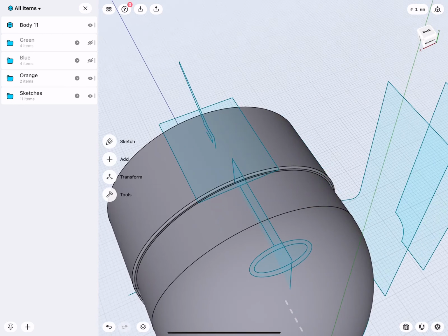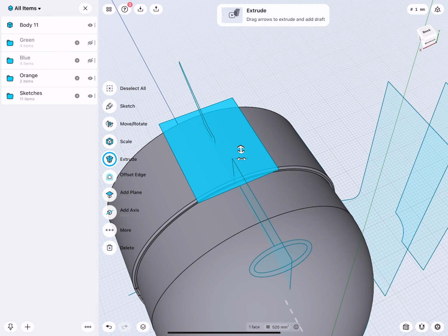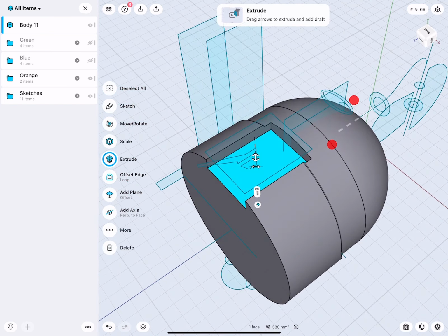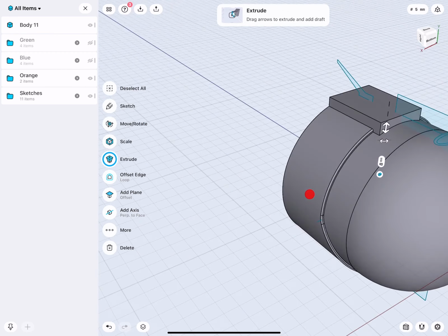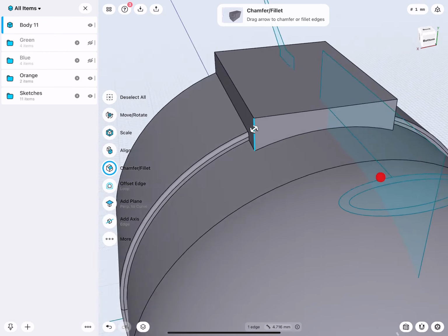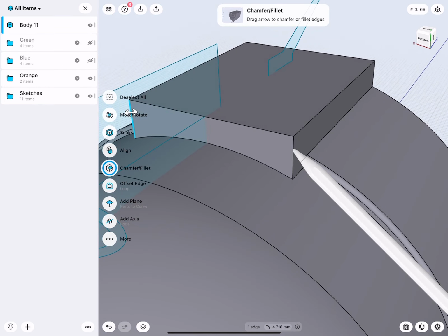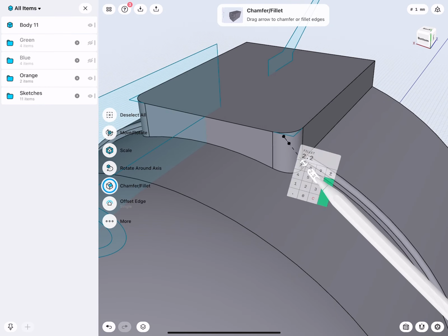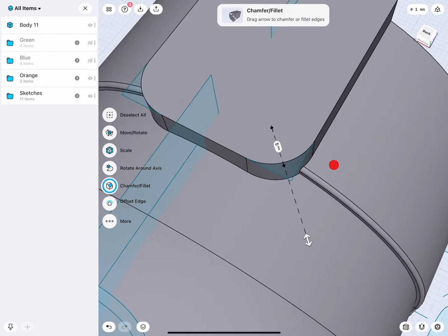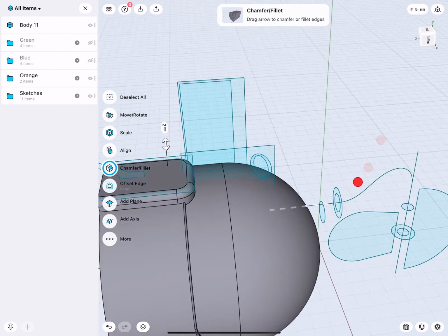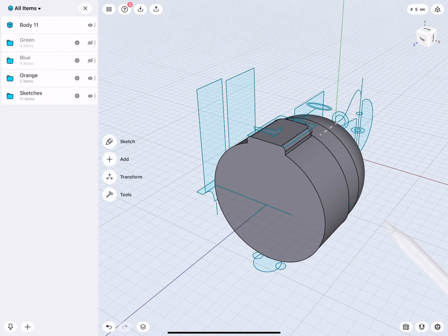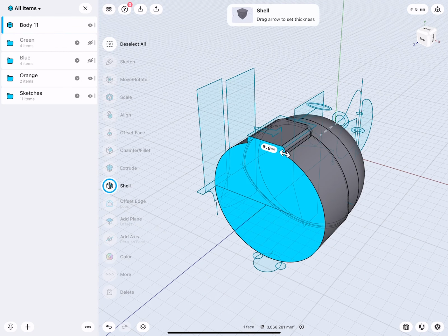At the back, there is the rectangle to create this flat surface, which is nice to put the suction cup onto it. So on this one I select, extrude into it, but instead of cutting, I would like this to join. Then again, filleting strategy. First round one set of corners by 5. This looks good. Then I can round another set of corners by 2. Very nice. Okay, so let's see, how does this look when we do a shelling now?